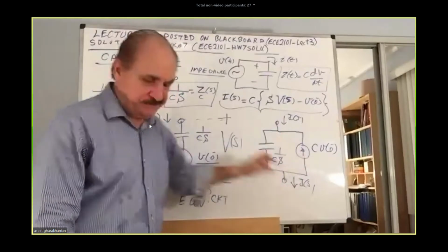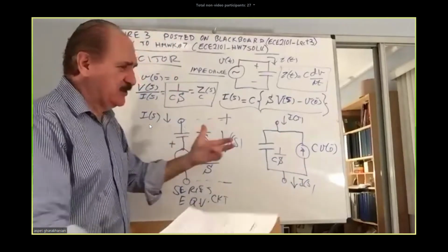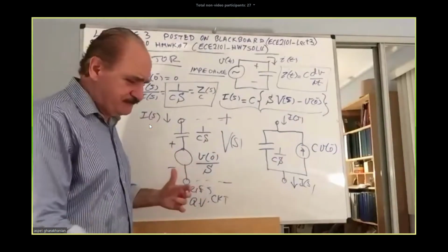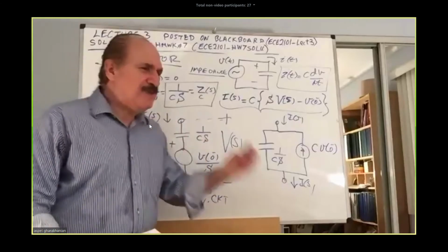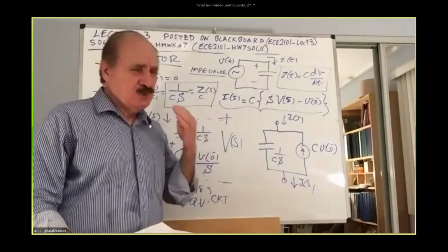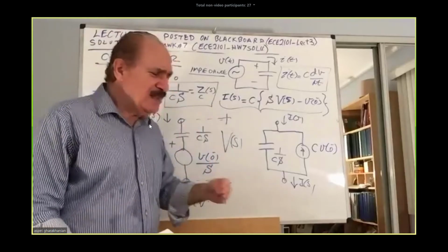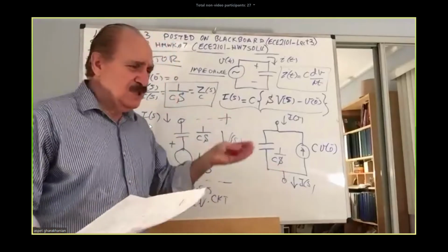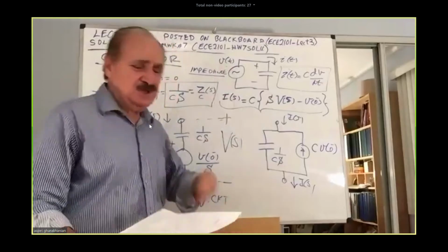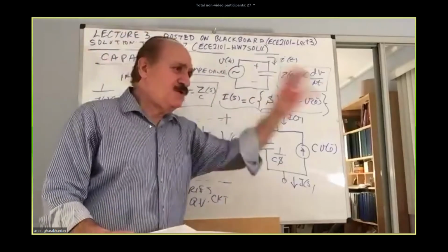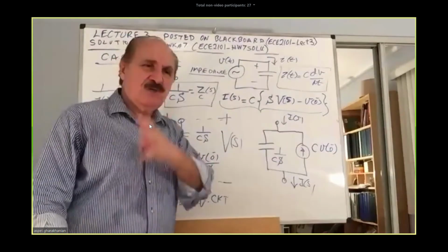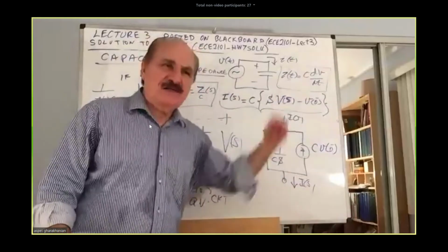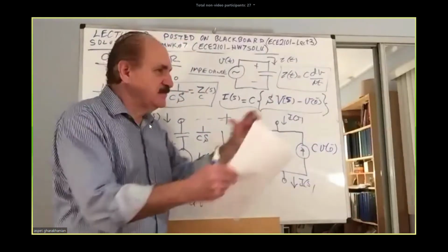For a resistor, simply it was a proportionality, just R. You can perform circuit analysis, applying all the rules that you learned about KVL, KCL, impedance, voltage, current multiplied by the impedance is the voltage, etc. So all the analysis that you did in the DC and carried over to the AC can be carried over to the Laplace. Same procedure, same techniques.